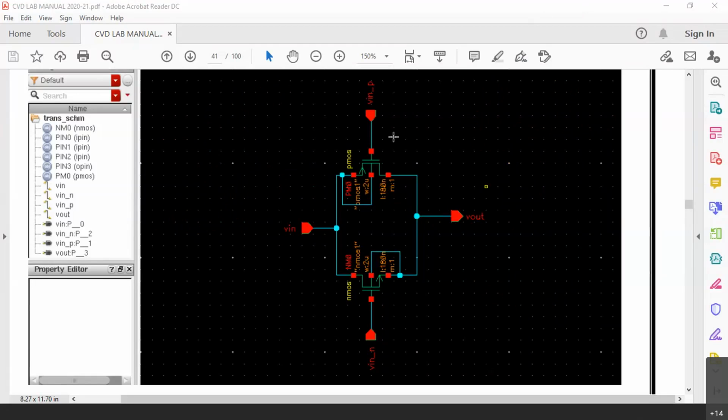When the circuit does not have a power supply, if the input is a weak signal with weak current, it is going to be passed over to the output. Only thing is, Pmos will pass strong 1 and Nmos will pass strong 0. That's all. Otherwise, this is not a buffer. So a transmission gate cannot be used as a buffer. I hope it is clear.